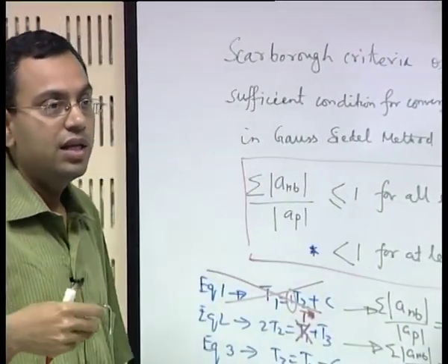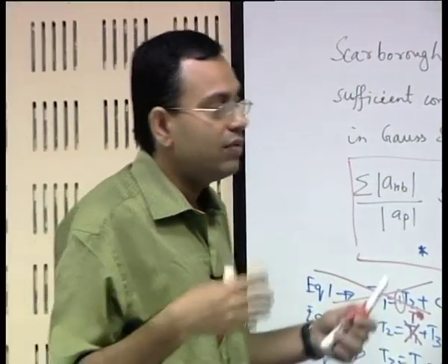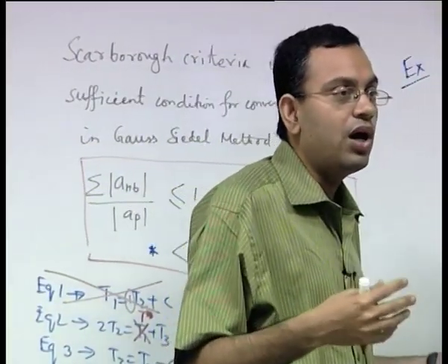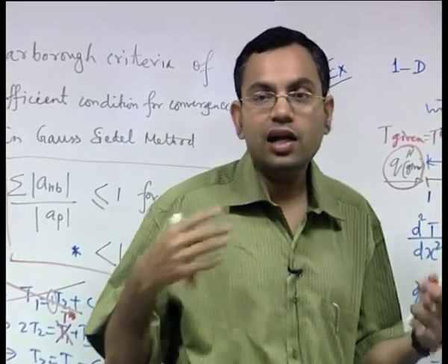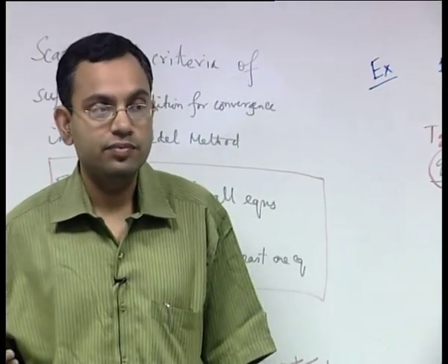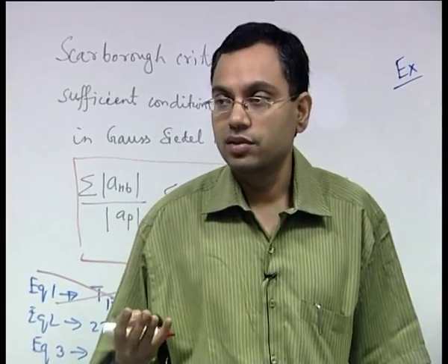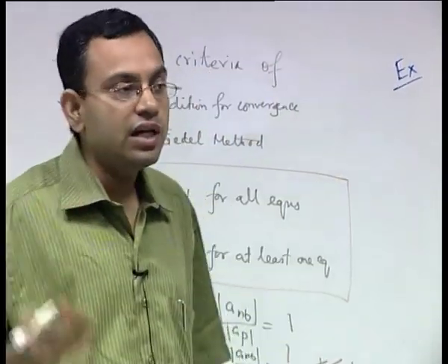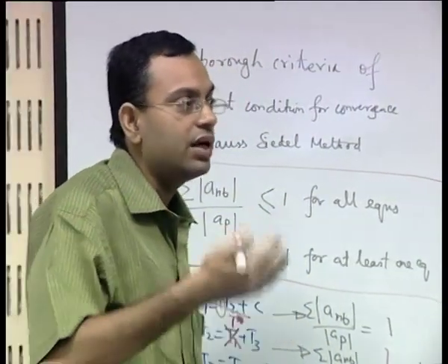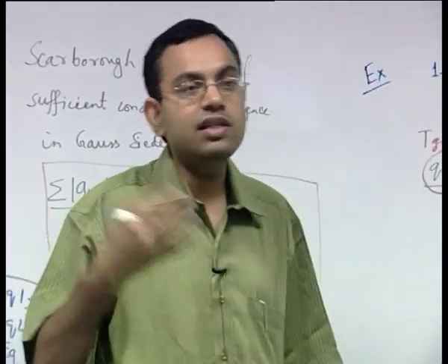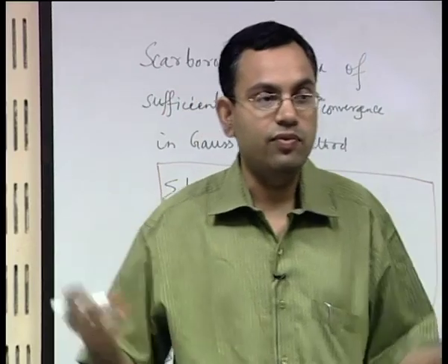That is where, in CFD, most of the times people fail in solving the problem because of an error in correctly giving the boundary condition, because most of the time you are solving the same equation. Either it is a diffusion type of equation, then we will see in our next chapter that it could be a convection diffusion type of equation, and then the Navier-Stokes equation, the fluid flow equation.